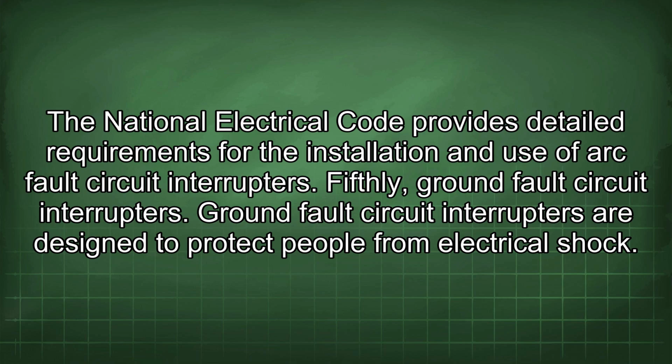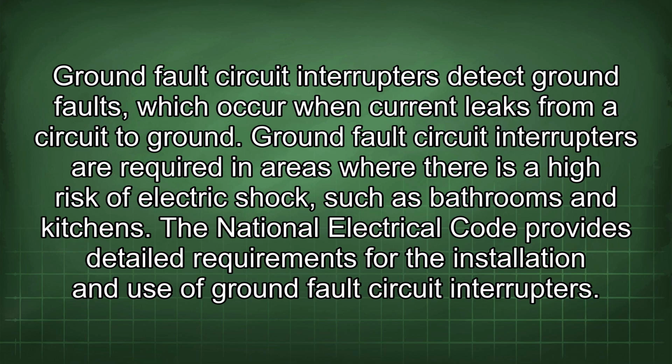Fifthly, ground fault circuit interrupters. Ground fault circuit interrupters are designed to protect people from electrical shock. Ground fault circuit interrupters detect ground faults, which occur when current leaks from a circuit to ground. Ground fault circuit interrupters are required in areas where there is a high risk of electric shock, such as bathrooms and kitchens. The National Electrical Code provides detailed requirements for the installation and use of ground fault circuit interrupters.